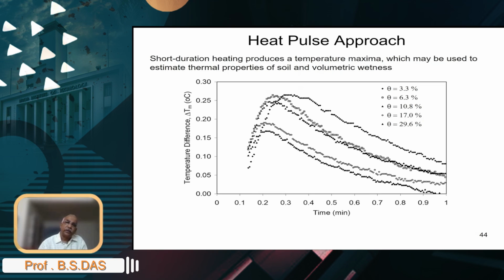So you will see a temperature time curve, and getting the temperature maxima and the time to reach that maxima can be used to indirectly estimate how much water content is there.